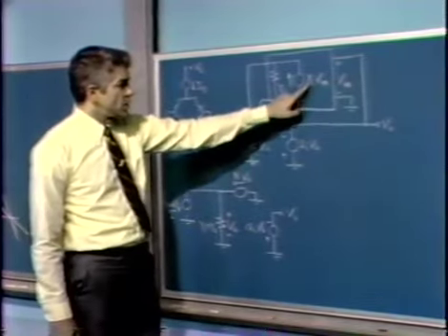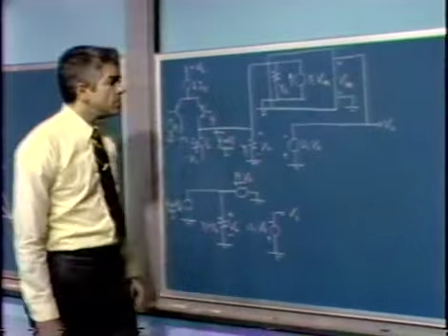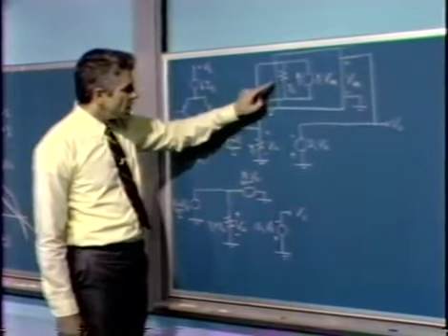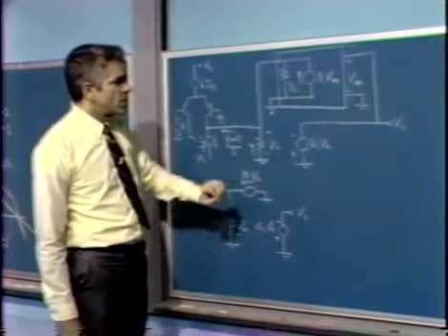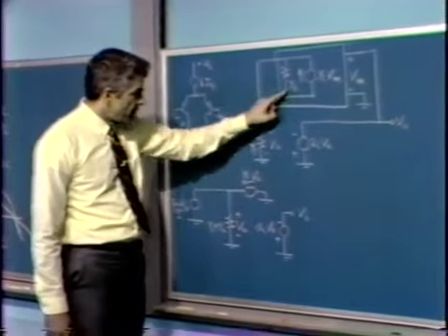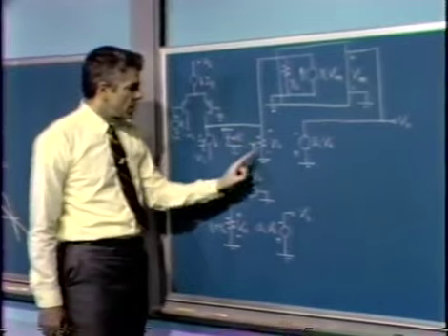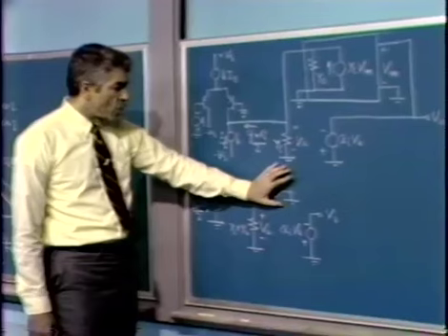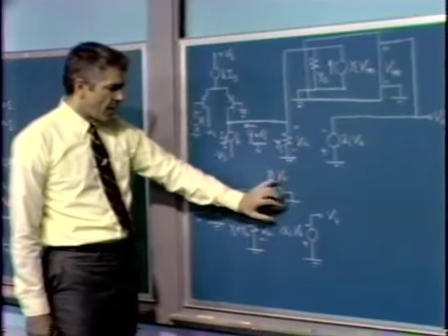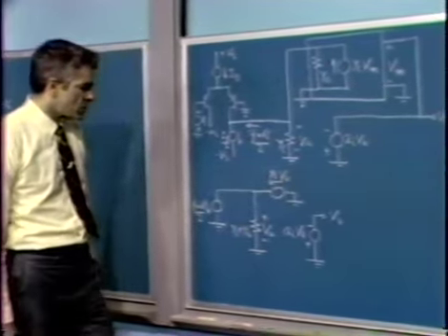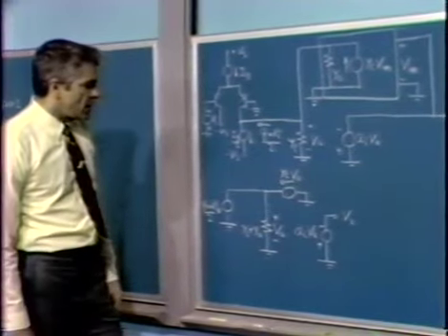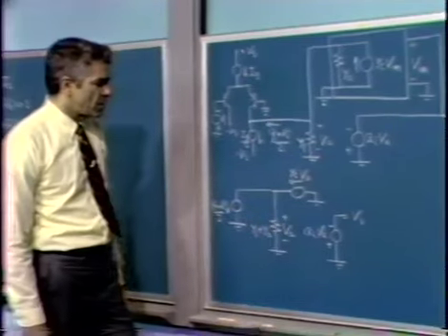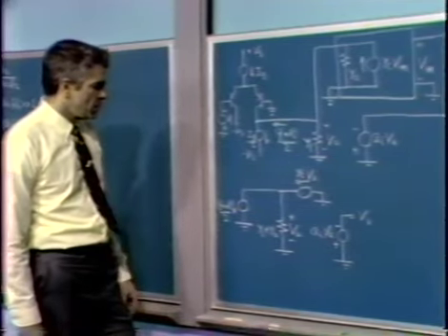That would, of course, disable this generator since VM would then be 0. However, we would keep the loading associated with the two-port network. We lump that admittance Y sub A with Y sub I to say all we've done really is make YC, or the magnitude of this generator, equal to 0, and then calculate the gain that results in the absence of minor loop feedback. Disabling this generator effectively makes F in the minor loop 0.